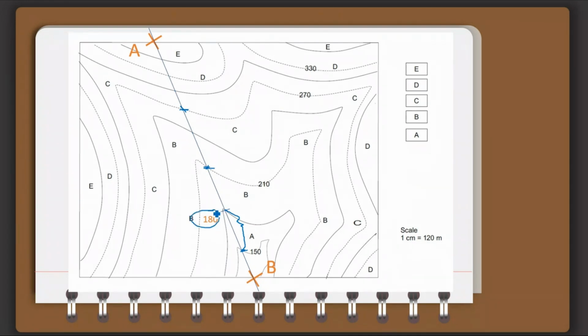So I am taking this value, this is 180, and here I am taking this value, it is 240, because it is between 210 and 270, and I am taking the one between 330 and 270 as 300 meters. So I take that same strip of paper. I am having the first lithological contact, that is between rock type A and rock type B, at what height? At a height of 180 meters.